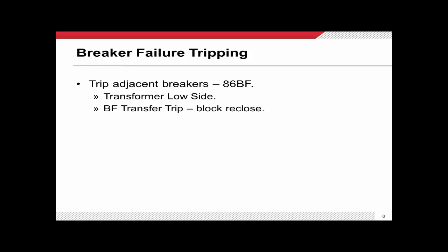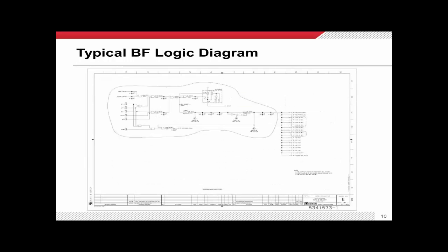Okay, again, adjacent circuit breakers, you've got to make sure that you're tripping the low sides of your transformers and the far ends of your transmission lines. And on the transmission line part, again, we will cover that in a couple of classes.